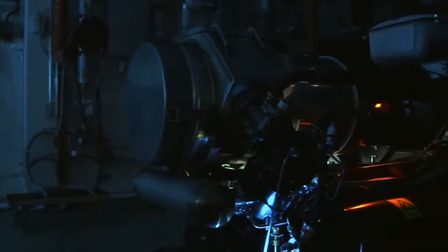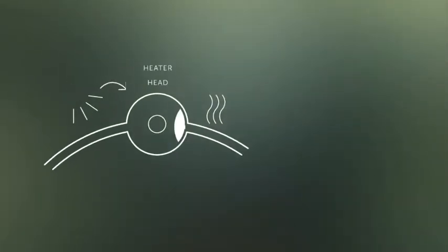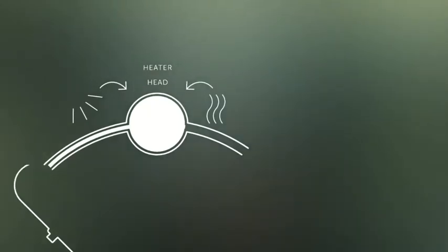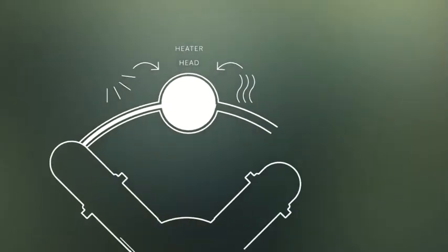This is our gas box. The same Stirling engine is sitting in the solar solution, the CSP solution. The basic principle of the Stirling engine is that you have a working gas. This working gas you heat up and you cool down. By doing so, you expand it and contract it.